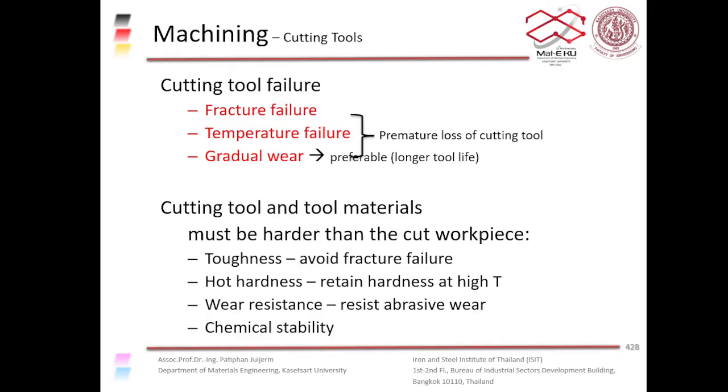So the cutting bits are plastically deformed, and you have a loss of sharpness. This is called temperature failure. When the temperature is too high, you have a loss of strength and a loss of hardness.